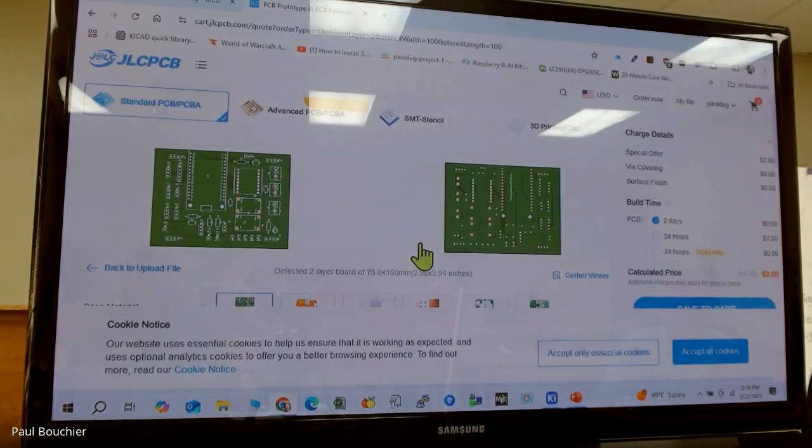The whole point I'm getting at: would this be a workable PC if you really just said screw it and send it? Probably. But some errors are easy to fix, so go do it. Now I have to figure out why we got a 3.3 and a 5 volt in copper. That really suggests that whoever put this together screwed up, because that is not going to happen in KiCad. I'm looking at the 3.3 volts, it's on the copper layer. Can you switch it over? Okay, so now you'd have to rerun the Gerbers.